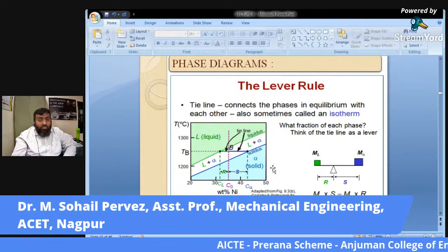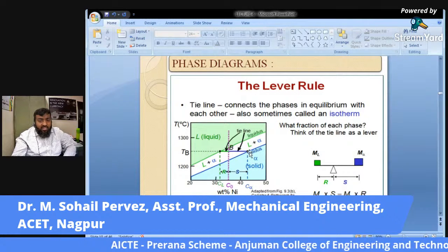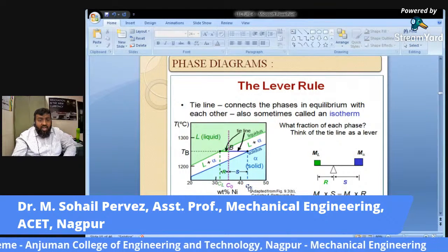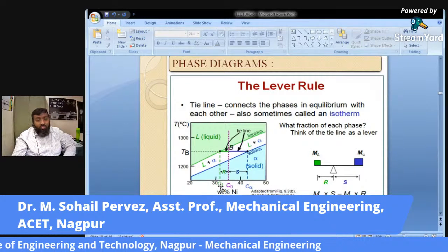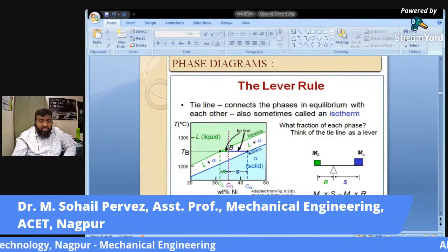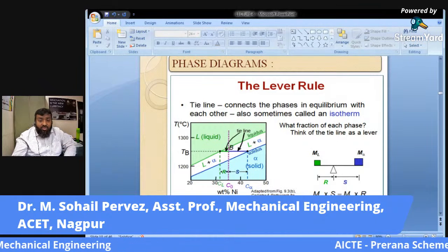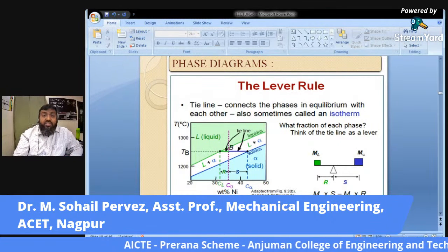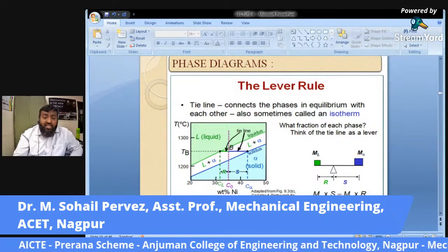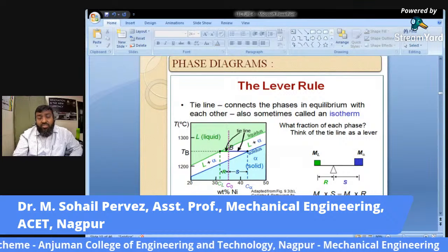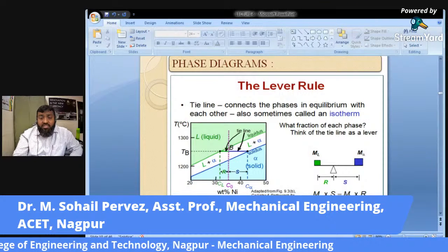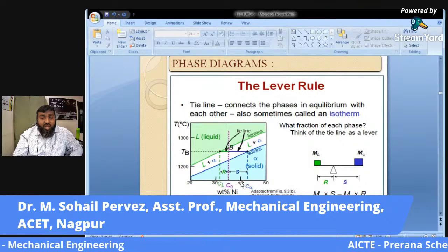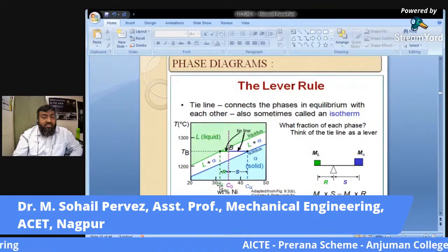So the point at which solidus line is cut is generally represented by C alpha, that is solid component percentage composition, and CL, liquidus percentage composition. So the formula would be for liquid, we'll try to remember this as WL or ML, sometimes it may be ML, in some books it is referred to as ML, somewhere it is WL. So in that case, that mass fraction will be represented by the equation C alpha minus CO upon C alpha minus CL.